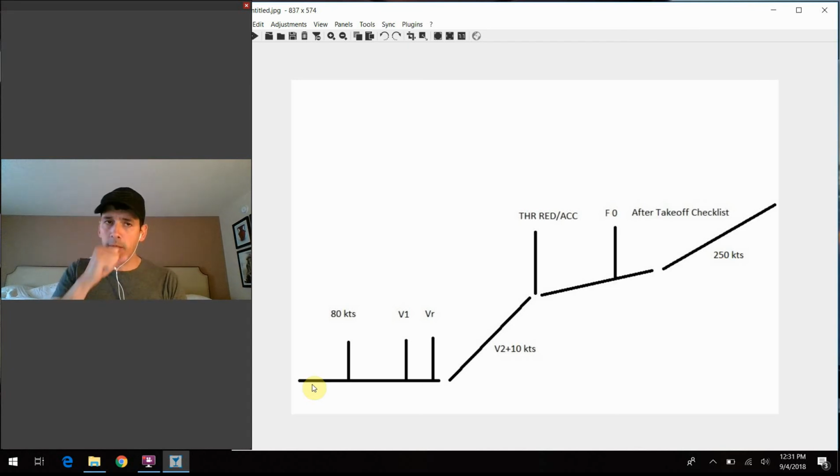So there's essentially a lag time from when the core of the engine comes up to speed and starts directing the air in the way that it does. There's a lag that it takes to accelerate the N1 section up to the appropriate velocity that it should be at to generate the thrust that we need for takeoff.